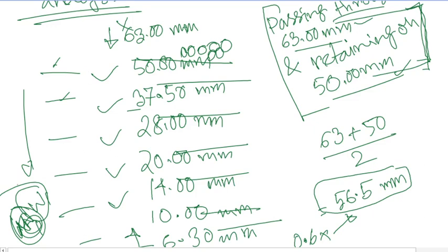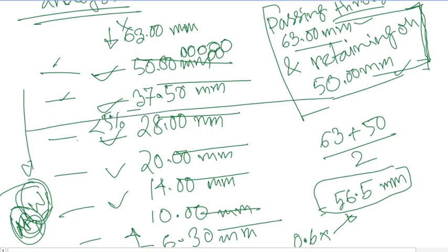With respect to W1, if any of these sieves contains less than 5% of W1, in any case we will be totally ignoring that particular row, and we'll be treating the remaining sieves for the calculation of our index.